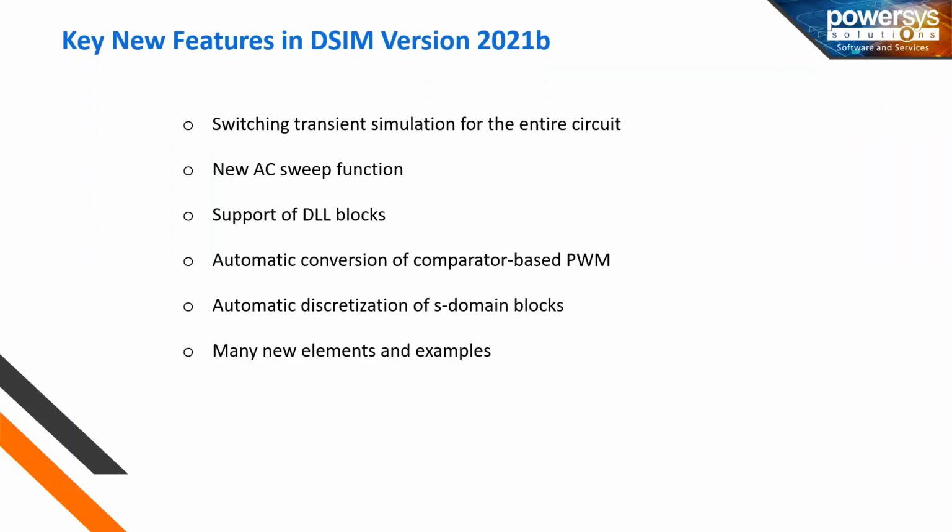So that's why we added the switching transients in the entire circuit. Previously, the switching transients were only inside the switch module. I'll show in the coming slides how this will be available. Earlier we could only see ideal waveforms, but in this latest version, we added the switching transients. So this will enable you to study the conducted EMI part for larger converters quickly and effectively.